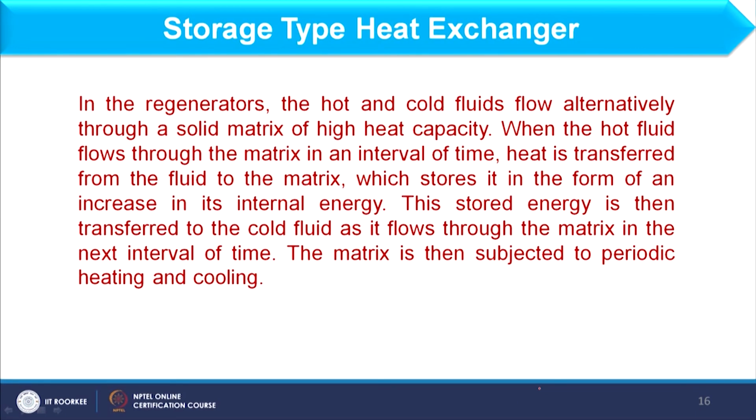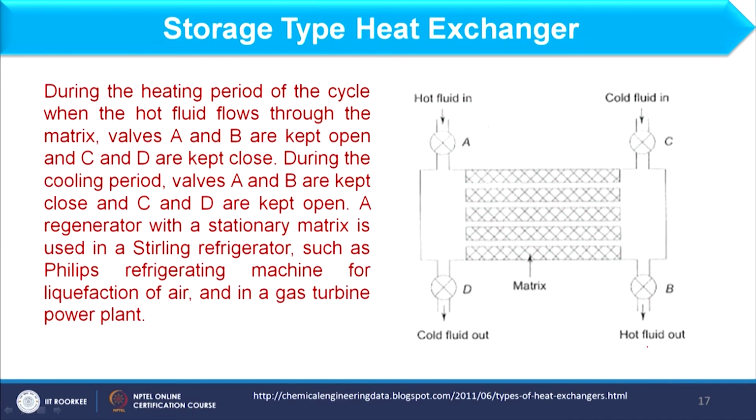And now we will focus on storage type heat exchangers. These are basically called regenerators, where hot and cold fluids flow alternately through a solid matrix of high heat capacity. To illustrate that, let me focus on this image. Here in this heat exchanger we have the solid matrix, with a zigzag formation.